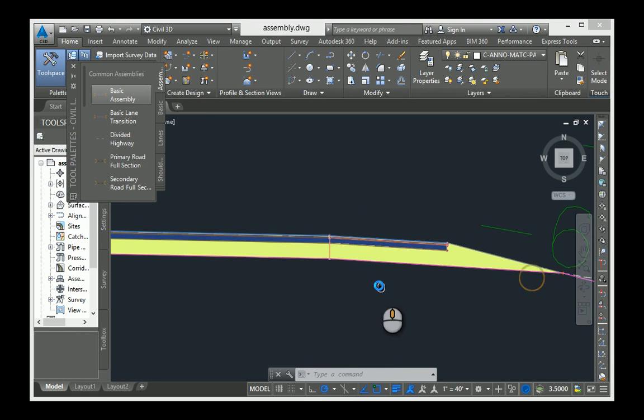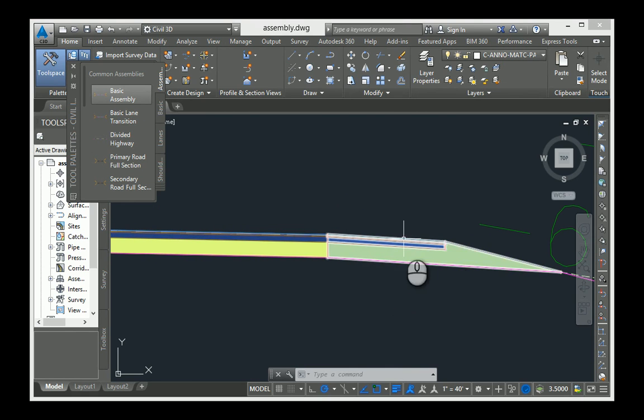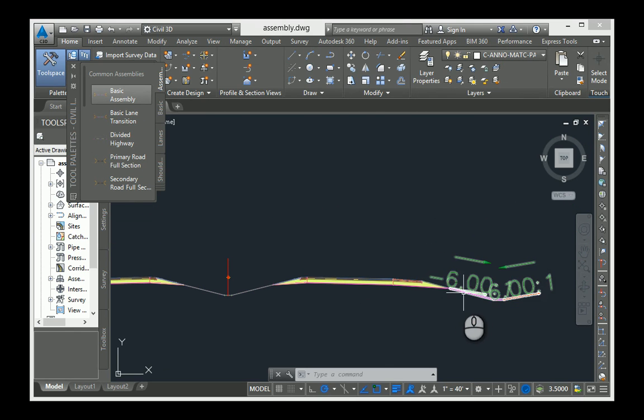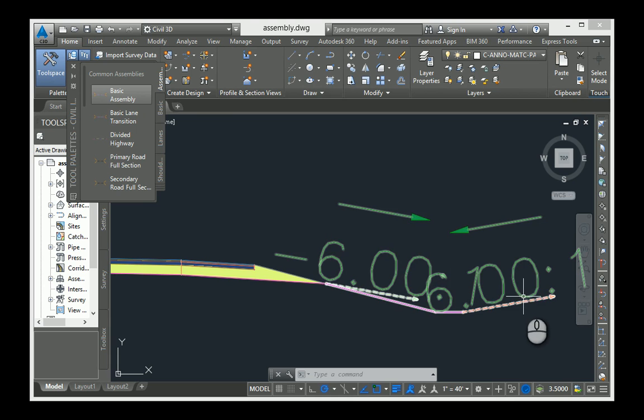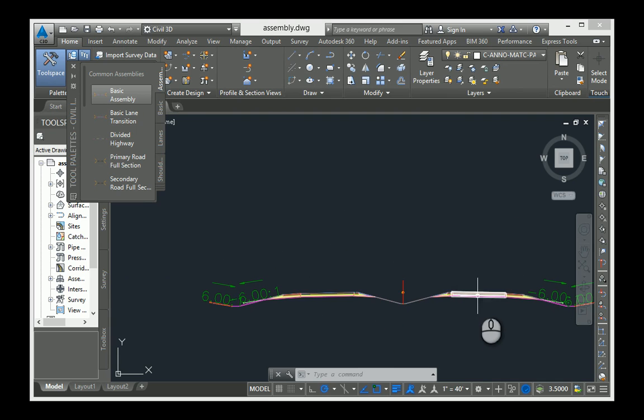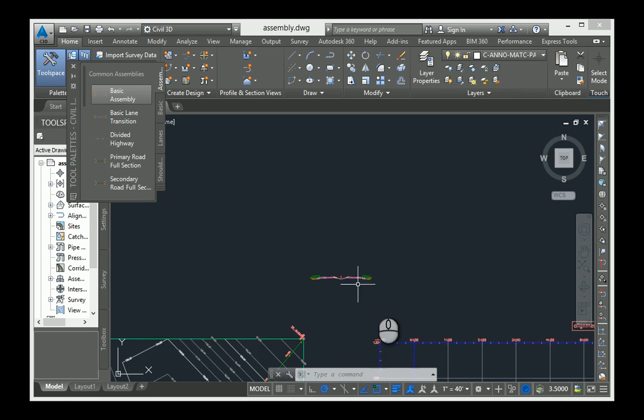This is the emergency lane over here on the right hand side, sloped a little bit more, and then this is the shoulder sloping away down in the grass, and then there's a little ditch over here, and then it slopes back up to the existing grade. So we can change these slopes if we want to make the ditch sides a little bit steeper. We can change the cross slope across the pavement, but it's pretty standard. So we're just going to use this standard one right now.